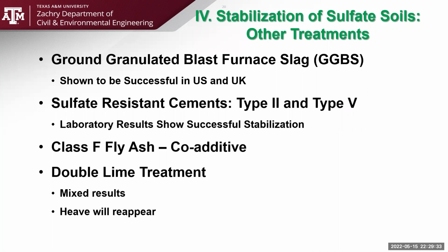Then you also have what we call lime with mellowing. Mellowing is an important process. Before you do curing, you mix the lime with water, leave it for a certain duration, and then come back and rework the soil. So lime with extended mellowing also works reasonably well in sulfate soil conditions supporting your roads. Okay.